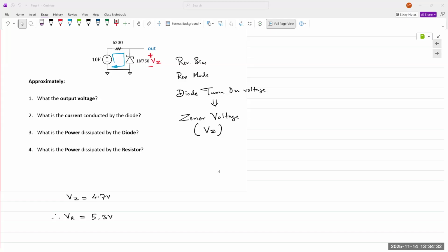If voltage increases and resistance remains the same, the current must increase. So the current increases through the circuit. The diode, being a nonlinear device, will accept more current flowing through it, but it'll keep the voltage constant. The rest of the voltage is dropped across that resistor. So the resistor voltage correspondingly increases and everything is balanced out.